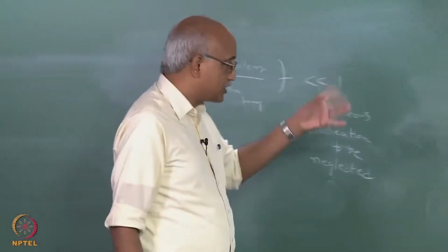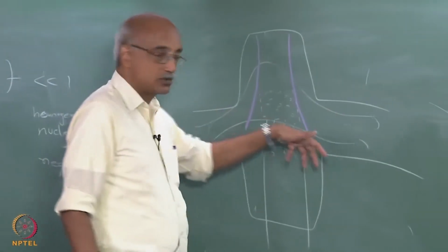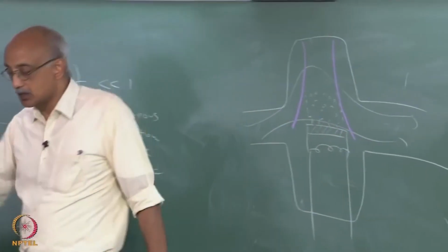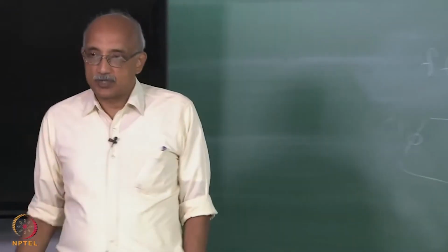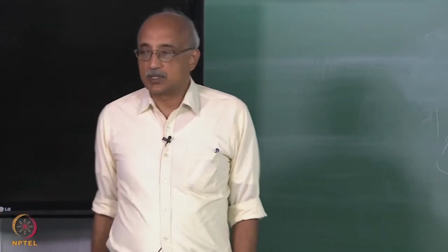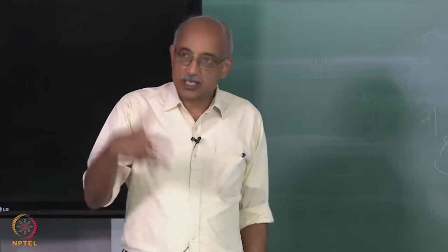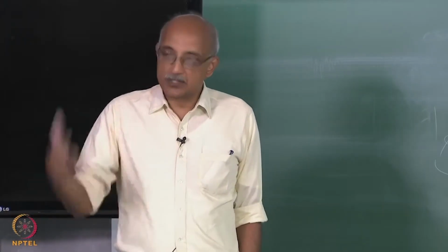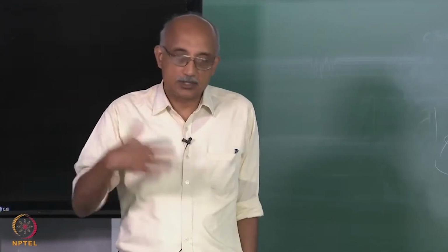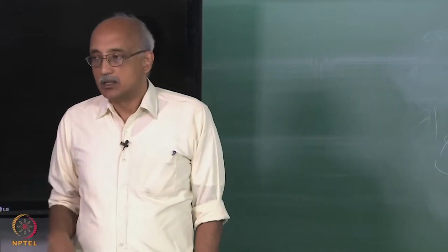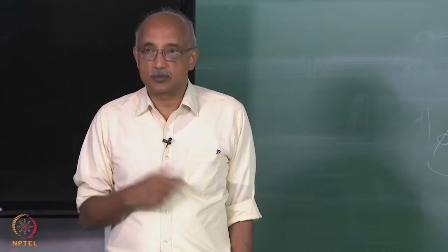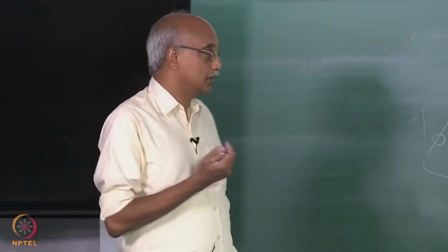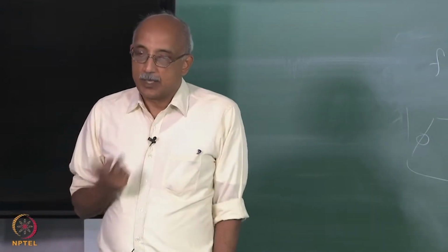So, simply by changing the configuration of the CVD reactor to a stagnation point reactor rather than a horizontal flow CVD reactor, you can improve the capture efficiency by 2 or 3 times, because even if the first capture efficiency is only 10%, if the same material is directed again 3 or 4 times, the overall capture efficiency can increase up to 30 to 40% even in an aerosol CVD reactor,